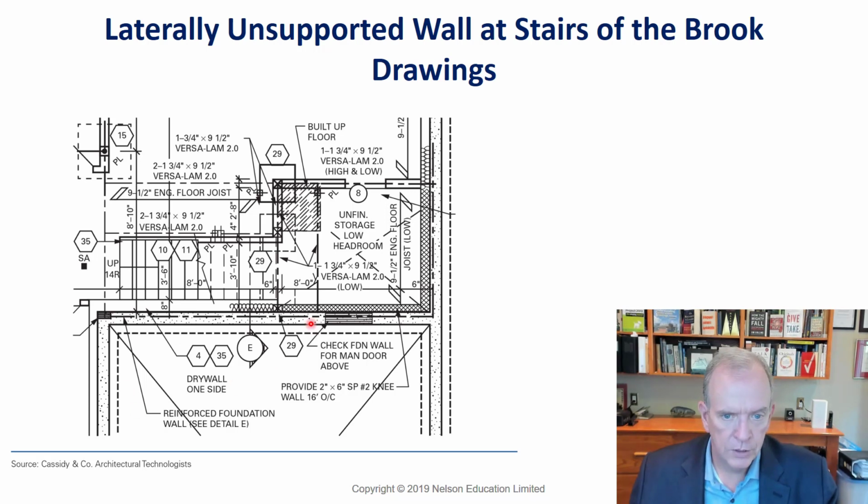Another example here, just illustrating where that would occur. So you'd check the foundation wall if you have to have a cutout in this particular case for the foundation wall. Also, in this section here, you see that there's this little dashed line here. This stands for reinforcing rods. And the reinforcing is placed to stop this wall here, because the stairs is here, is considered laterally unsupported. So to ensure that the wall is nice and solid, we put some rebar in this section.